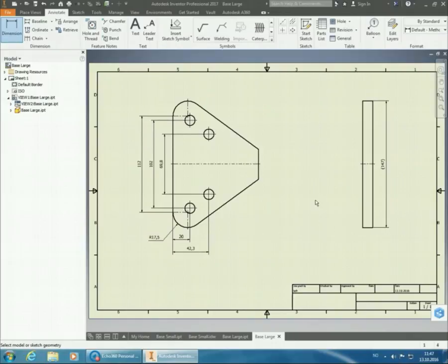But what is likely the case here is that you've gotten a hole pattern wherever you're going to mount this with the bolts on. So you have to have your holes in certain locations for them to match up with the hole pattern where you're going to mount it. And that means that you can end up having these point something dimensions. So it's not ideal from a designer's point of view to have dimensions like that, but sometimes you just have to. You're not able to change what you're going to mount it to.